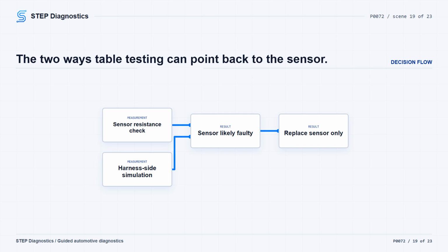the temperature sensor is likely faulty. The temperature sensor is individually serviceable, so if measured resistance does not meet the table values, only the sensor should be replaced and not the entire mirror assembly.